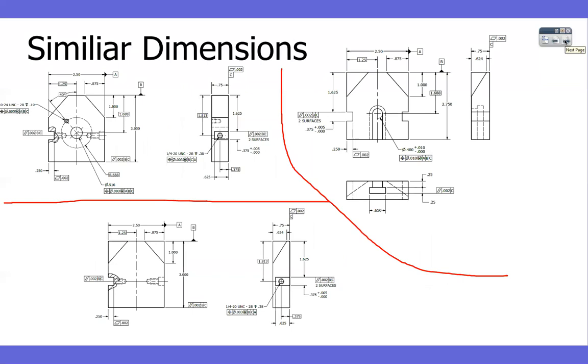When we have multiple parts that go together, they're going to be dimensioned the same way. So here I have 3 pieces that are from that vise, and if I look at them, this dimension is the same as that dimension, same as that dimension, right? Where the slot is, here and here are the same, right? They're both dimensioned from the top down. They look pretty similar the way they're done. Okay? You should see that on a set of drawings. If you see on a set of drawings that this one's going from the top and this one's going from the bottom, then there might be something going on. But seeing a drawing like this, now you can see, okay, that and that and that are all the same. That's going to line up. The person doing the drawing, if they do it this way, makes it easier for you to understand. But also, the tolerances, which we'll talk about next, all go the same way. Questions?